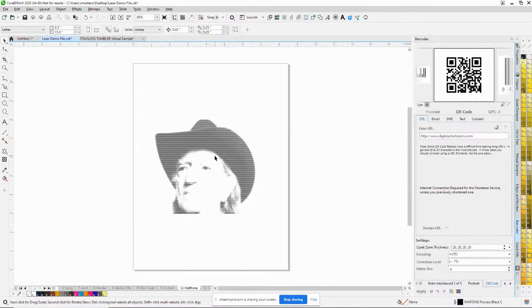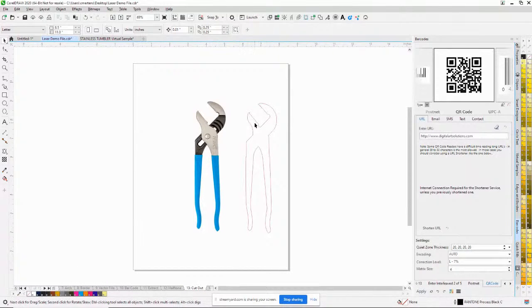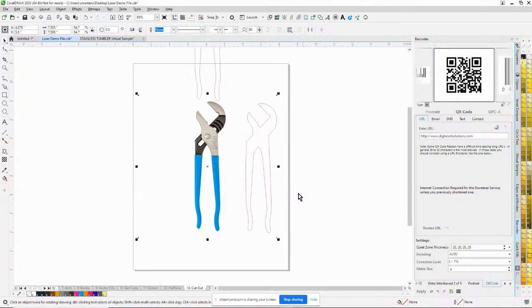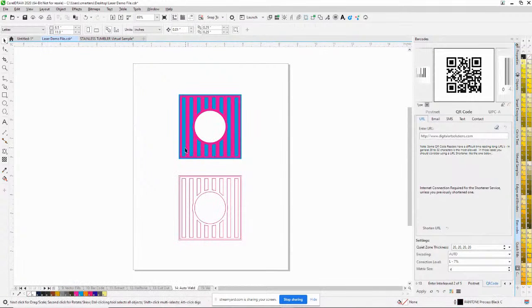We have a functionality for creating halftone effects from photos. This is our production software. I didn't really get into this, but if you wanted to contour that, we have a functionality in our production software called Stone Cut. You would just click on the contour, set in your parameters, and then apply your parameters. I did a slight inside bleed on that, so it's slightly inside the graphic versus being around the border. So these are the kinds of things that we do.